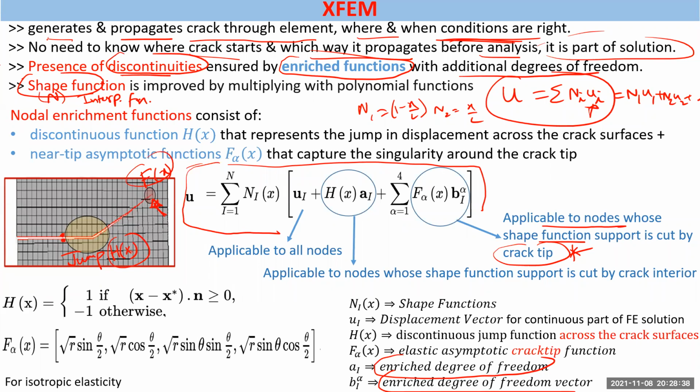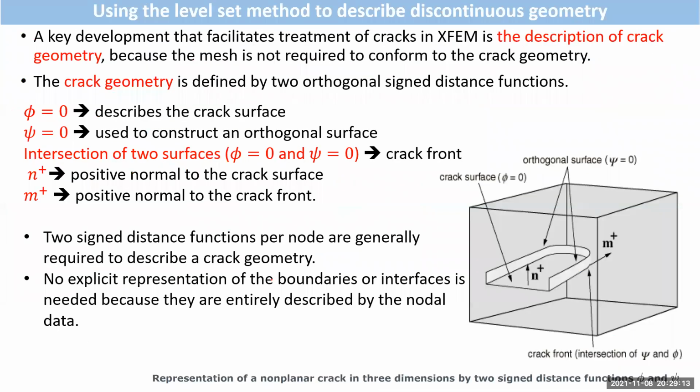How the extended finite element method is working in Abaqus is the same concept in ANSYS also. If you use some other software also, the theory part is the same. Extended finite element method is a technique, just like contour integral method or VCCT is a technique. So this part is same whichever software you use. So you have phantom nodes which have additional degrees of freedom, and those additional degrees of freedom will help in answering the discontinuity at the crack surface and also the singularity at the crack tip. Is that okay so far?